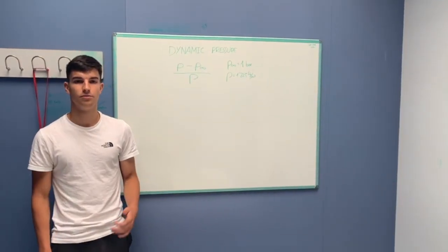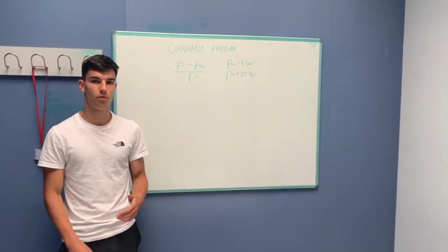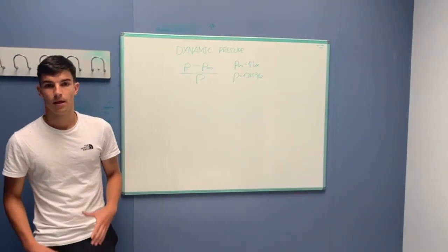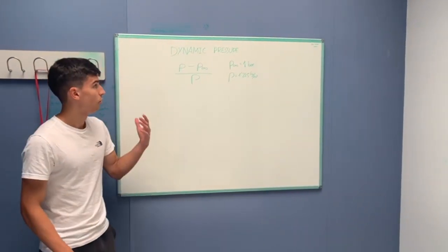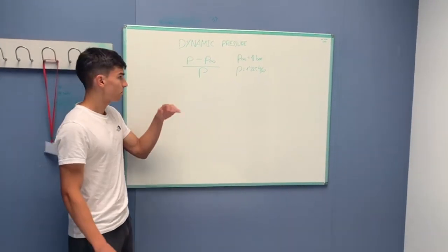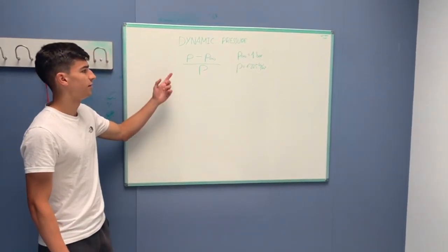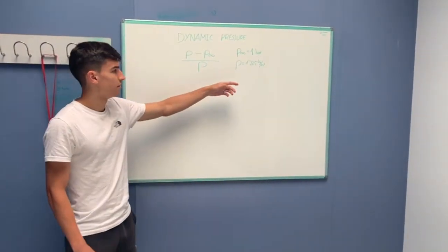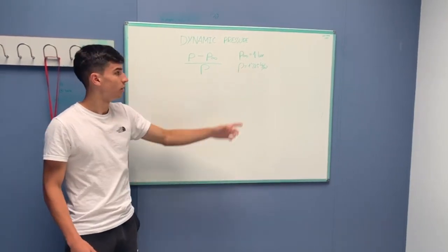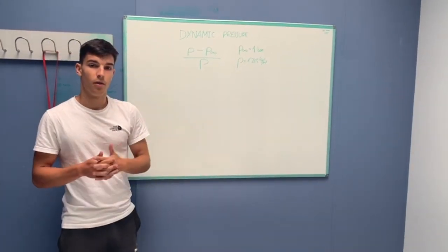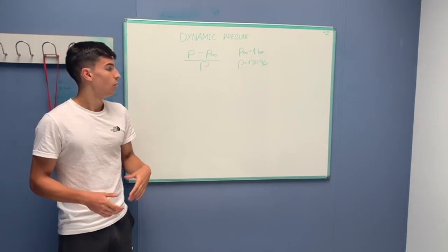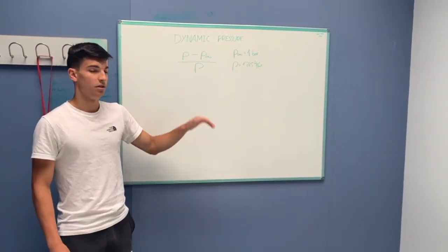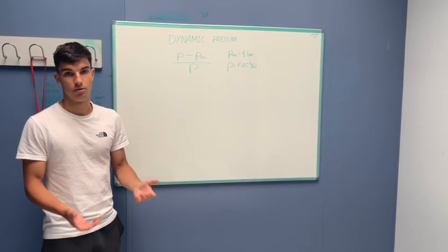It is important to take into consideration that when working with open flow, when we calculate the pressure, indeed we are getting the dynamic pressure. That is the coefficient between the relative pressure and the density. These are the values that we have used for the simulation, and even though compressible flow may appear, we've simulated it considering only incompressible flow to simplify the result.